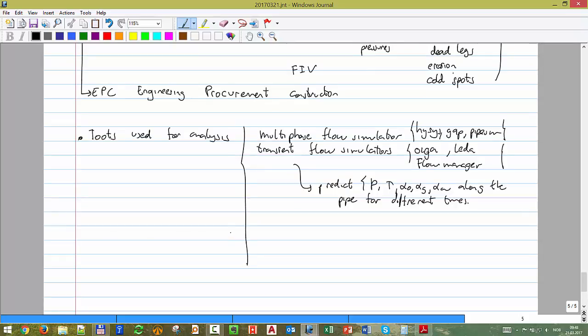Then we use, for all of that, we need PVT analysis, and this is basically split into two phases. One of them is the lab test. Okay, we want to test first what components do I have in my oil, and also make tests of what is the volumetric behavior of that oil. Okay, some depletion experiments,